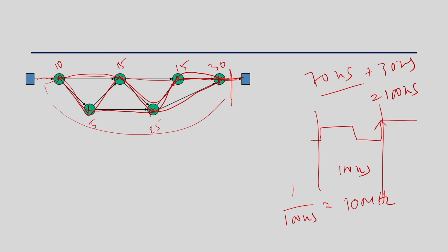You might do some kind of combinational optimizations here, but after a certain level, the circuit cannot be optimized further. The combinational optimizations I talked about in the previous 2 classes may not be applicable here, or may not be able to optimize this combinational circuit further. Okay. So, in that case retiming comes into the picture.